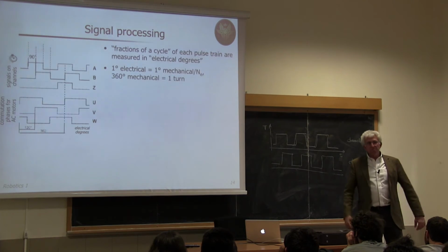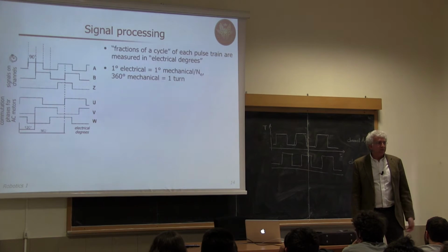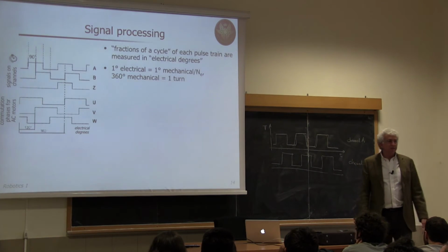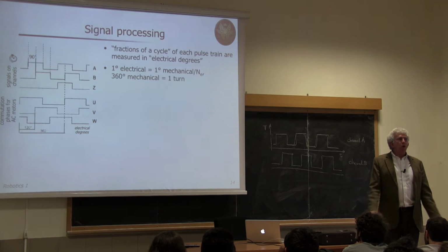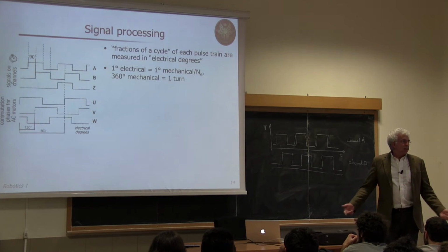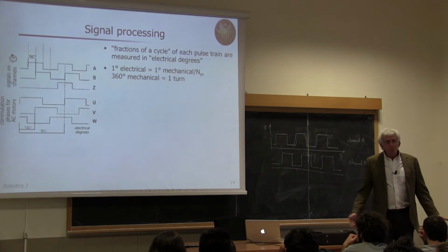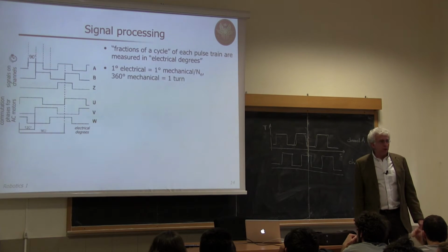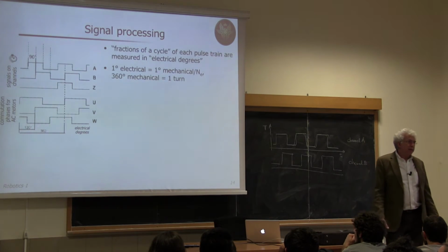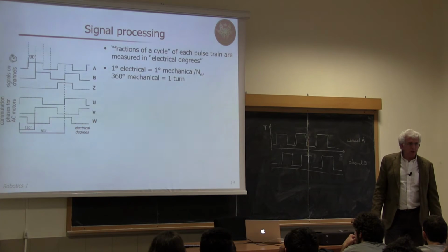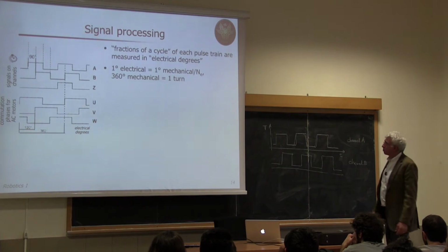It takes a few tenths of seconds, so let's say 20 seconds, 25 seconds. And when all the joints have been homed, this is the terminology, then you can start operation. It's a procedure that you don't have if the robot has only absolute encoders. It's only for incremental encoders.